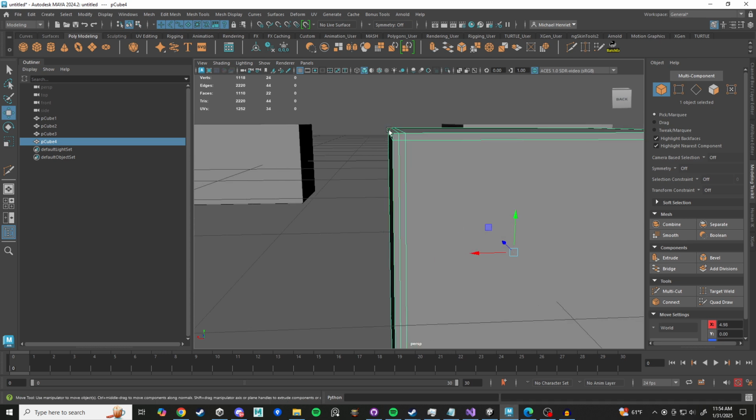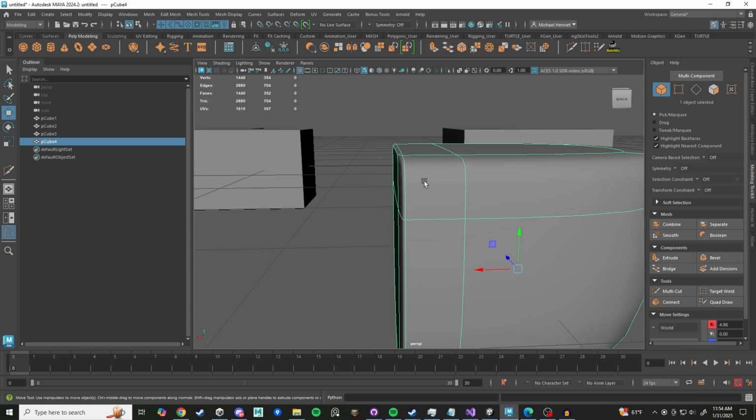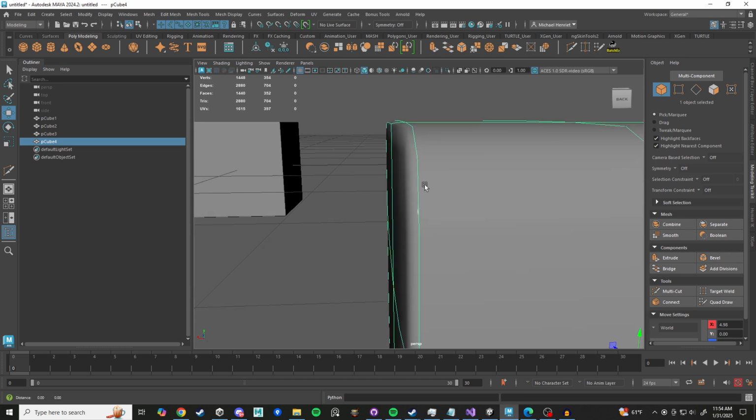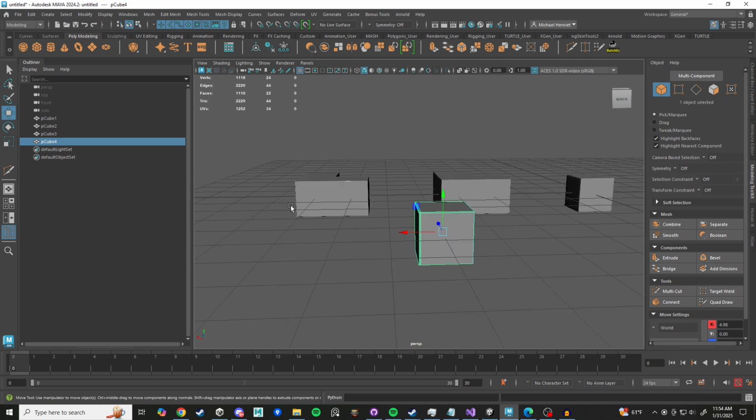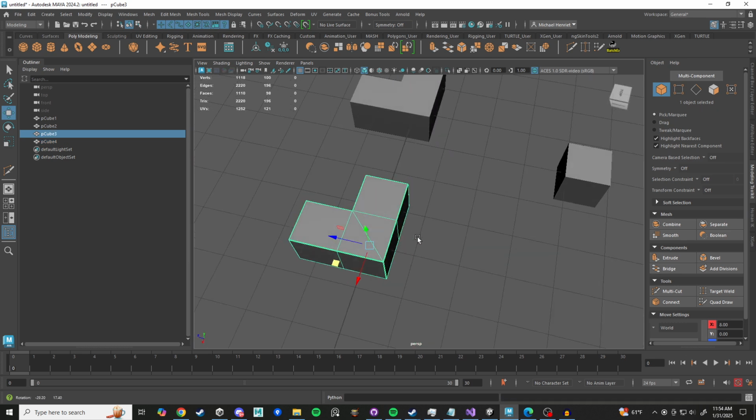This edge, even though it's at the same height, when it gets interpolated, look, it starts to slip a little bit lower. It's kind of hard to see with this, but look at that curvature there. It starts to slip down. So reinforce your edges where you need to.